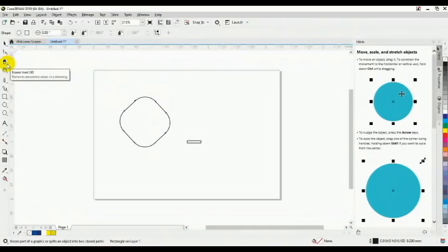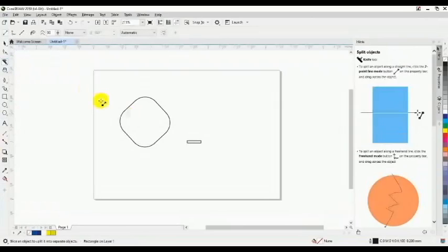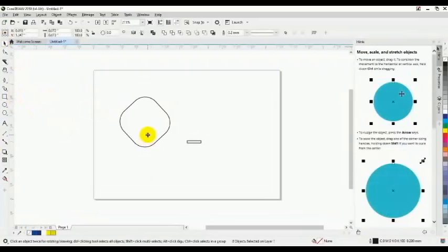And you move to this one, which is the eraser tool. We have crop. We use this one for the bitmap, and the knife we use to cut. For instance, look at this one now. Just use it to divide this area. Automatically it has cut it. If you want to confirm it, let me move it from the area.